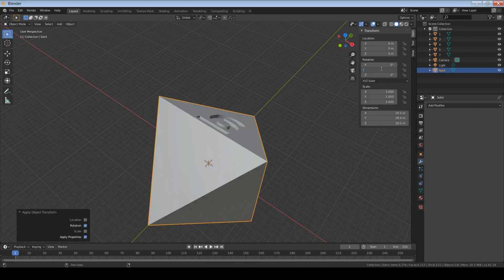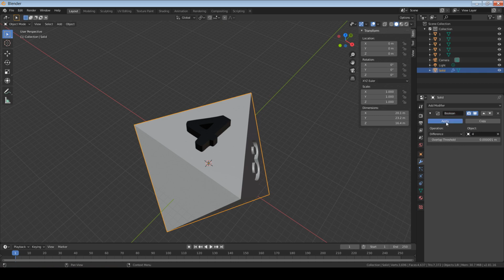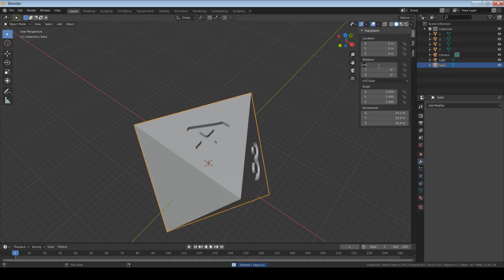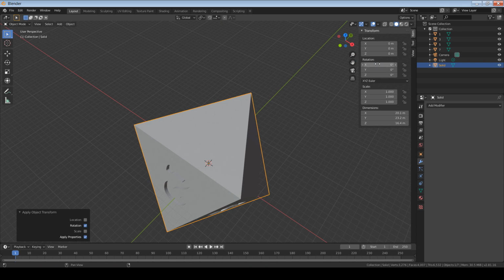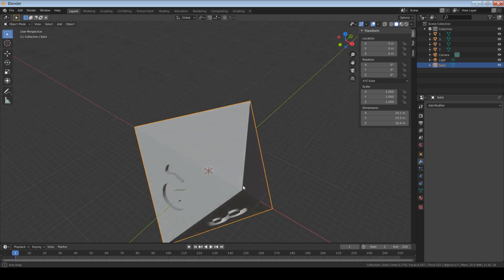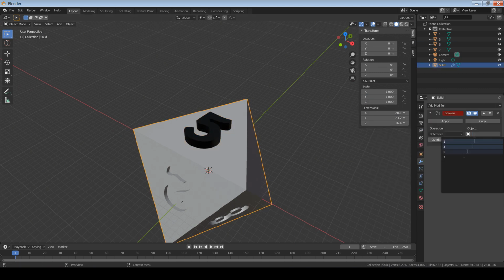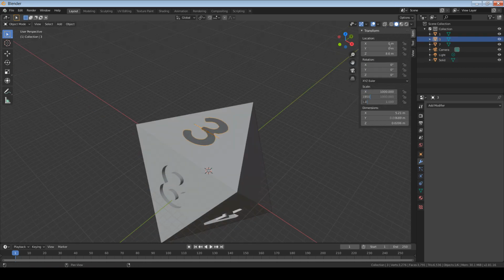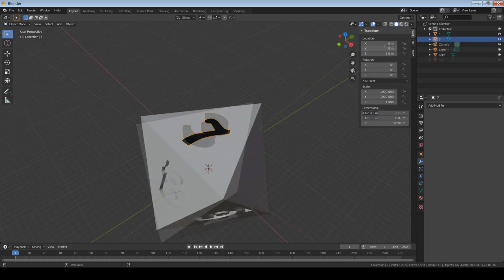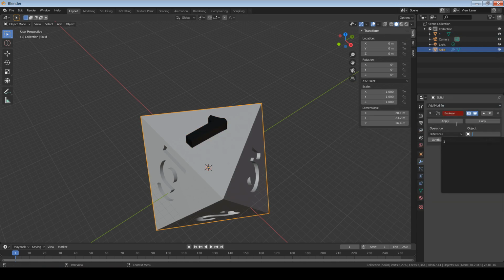Now on this blank face, I'm going to be doing the number 4, but after I complete this Boolean operation, I'm going to be rotating on X by 180 degrees. Keeping with the logic that I mentioned during the D6 portion, I'm going to be grabbing the number 5, since 5 plus 4 is 9, and then doing the same rotation and Boolean combination I did on all of the previous numbers, not including the 180 degree flip on X. The remaining numbers I'm going to be doing in the order of 3, 7, and 1, and of course if you want to follow along with that future video, don't delete the 1.